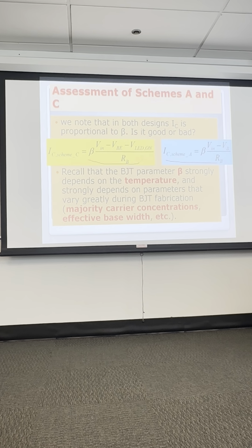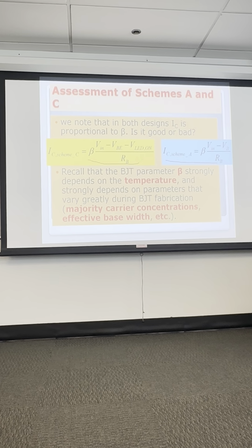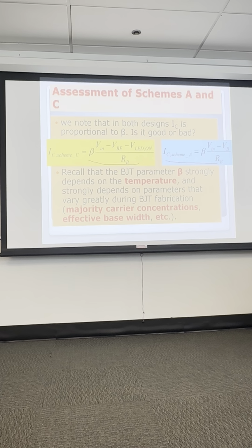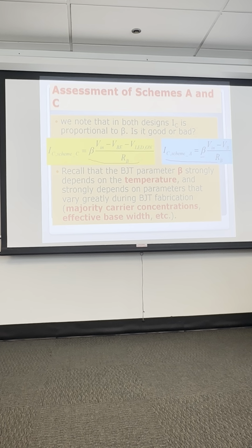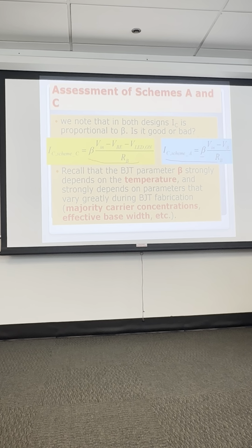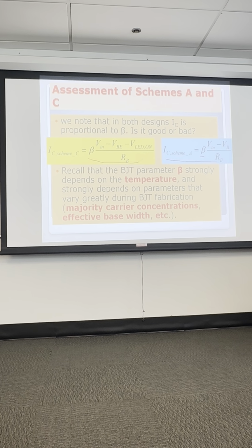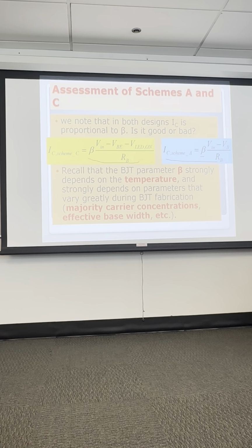And then the second, well, before moving over to the second one, we find that the collector current in the first circuit is very dependent upon the beta of the transistor. And we did not spend much time with the physics of the transistor network. What's the atomic structure inside the transistor to give beta? The beta can vary from 30, let's say, to 500. So that means the collector current here can vary a large amount directly with the transistor beta.